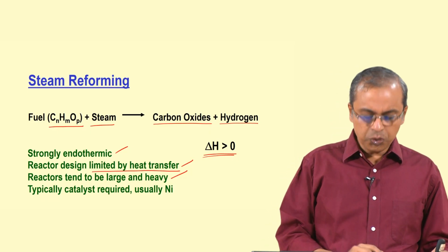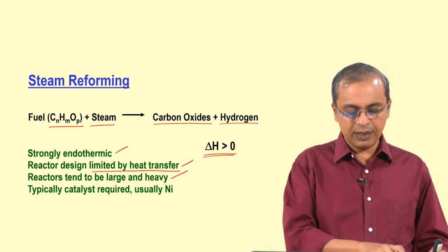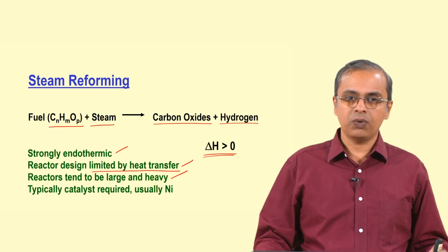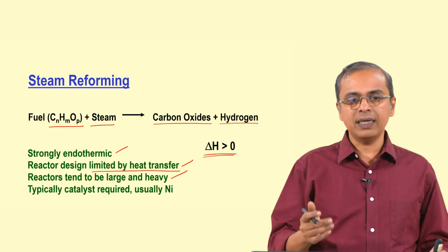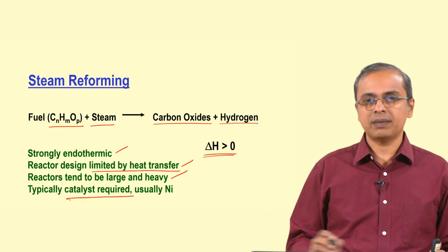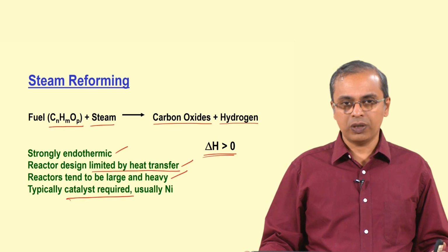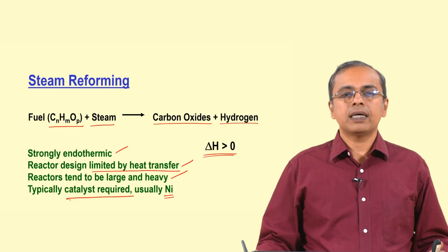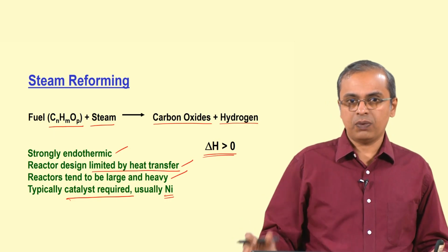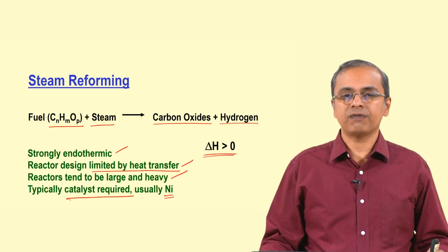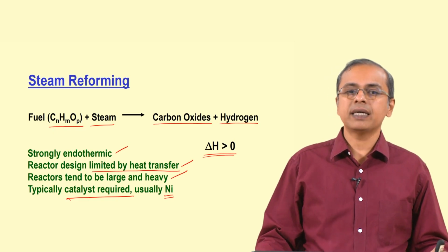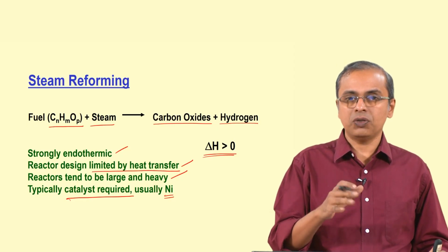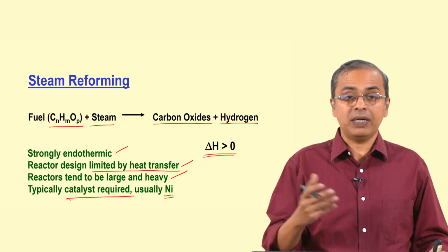Okay. And usually this will require some catalyst to enable these. You simply cannot just mix the fuel and the steam and expect things to happen the way you are hoping for. Usually a catalyst is required to ensure that the reaction occurs at some appreciable rate and in the manner that you want it to proceed, and typically that catalyst is nickel. So, clearly, nickel is not expensive, it is quite a cheap, inexpensive metal to work with relatively speaking, and therefore this is a very acceptable process. It is not prohibitive in some fundamental sense.